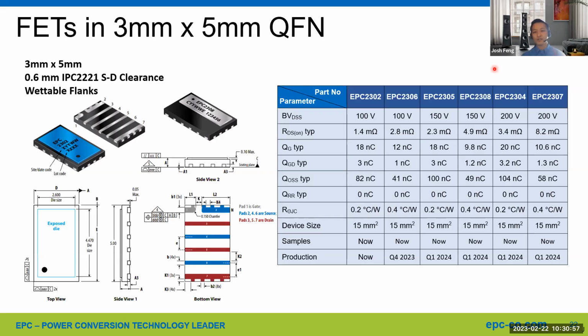So if for any reason you desire a lower voltage device, and for any reason you need to swap to a higher voltage, you can basically just desolder the device and put in a new higher voltage device. If you have some current sensing, you might have to adjust some current sensing limit.